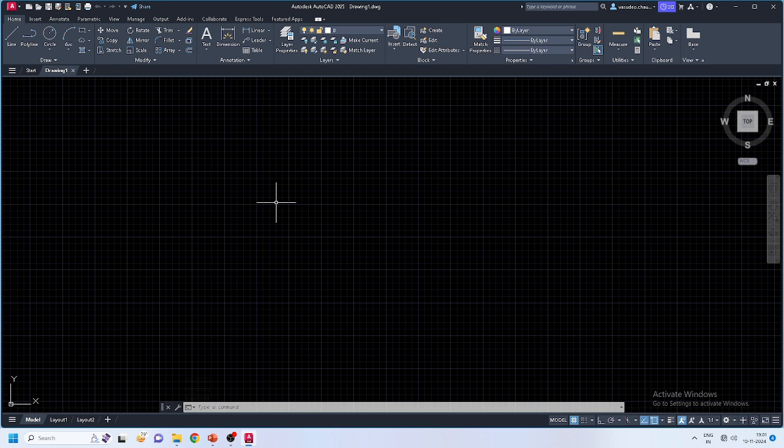Now when you are here, if you are working with AutoCAD for the first time, then maybe first of all you can change this background. Instead of black you can go with the white background. Why? Because most of the time when you take a print, the print will be on a white page, and then the color combination, if you work with the black background, may be a problem when you take a printout, right? So for example, if you use a light color line on a black background, that may appear good, but when you take a printout, it may be a problem.